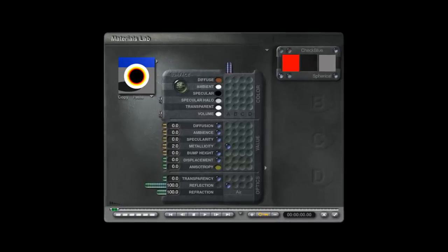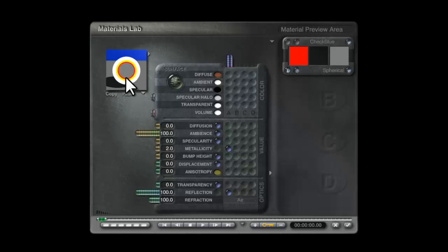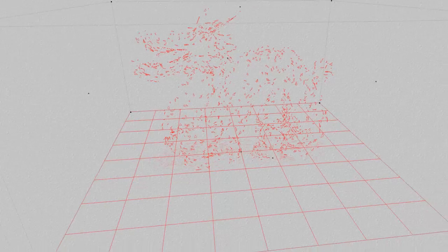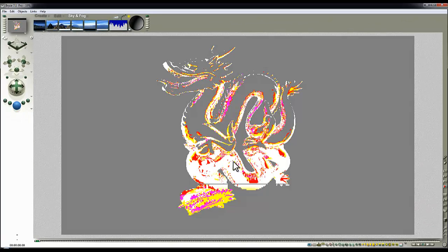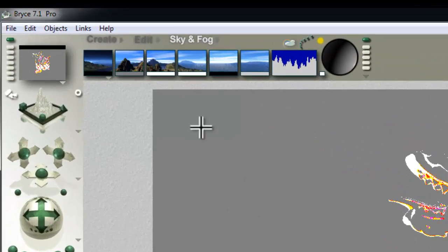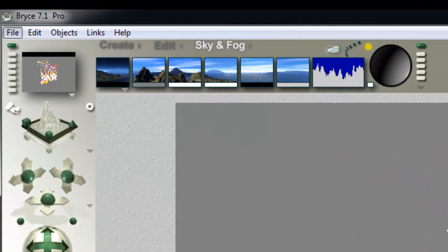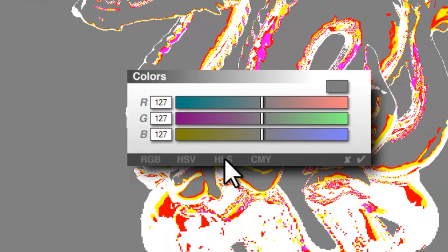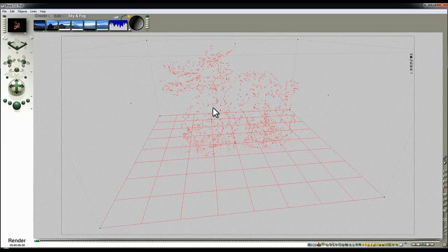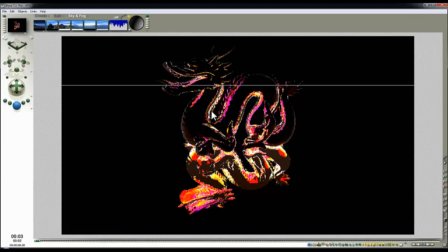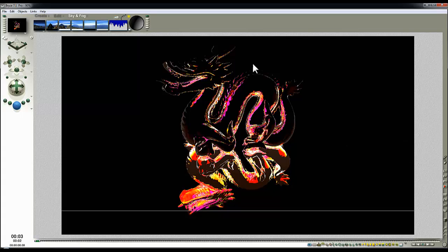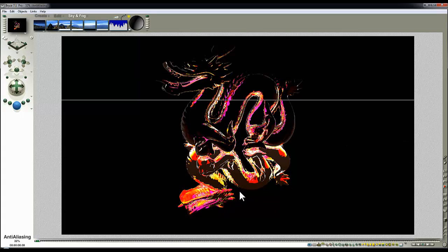And then I'm going to generate the light within the material by using the ambient channel. Now the ambient channel is going to light things up and make things bright again. But because this is a multiplying effect, I can take the global ambient control, which works through the ambient channel, and set that down so that the light output is very low. So it'll look black on the monitor. You won't really see this effect, but it'll be enough to drive the material properties. So now you can see we're getting a lighting effect from apparently nowhere that's coming through the reflection.